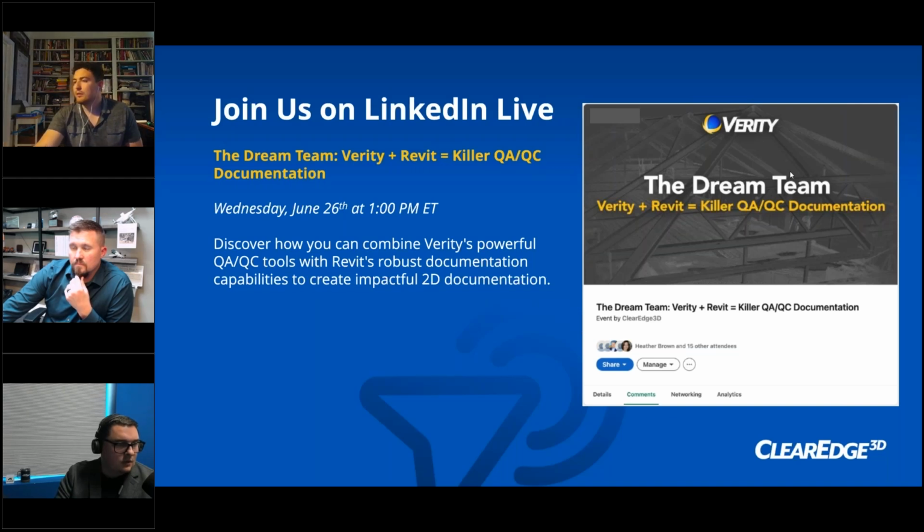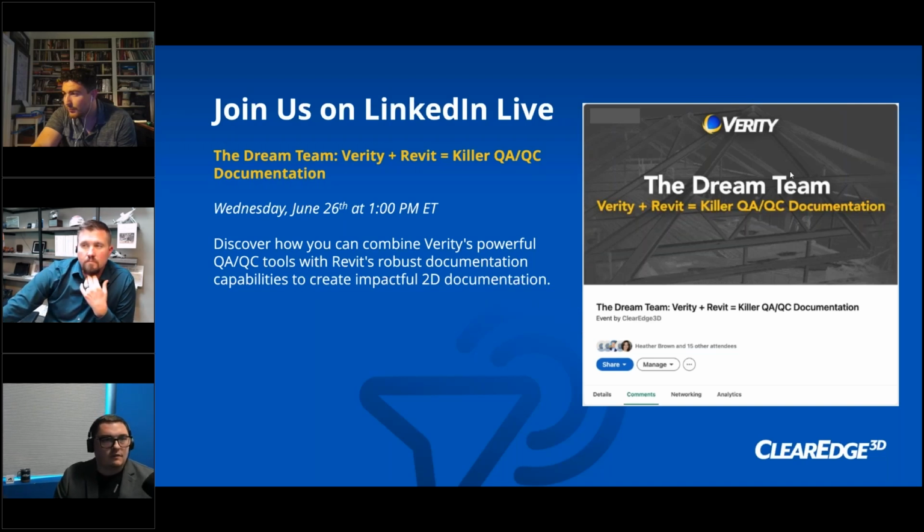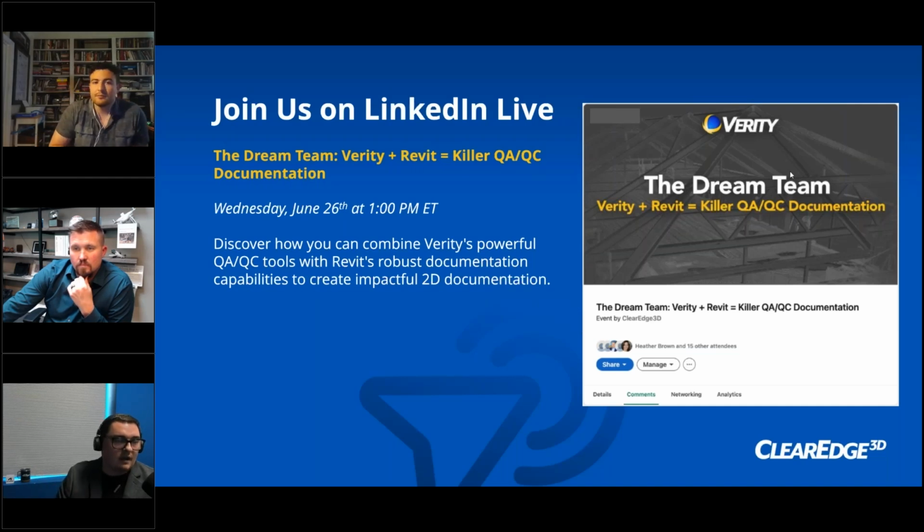And then I saw a question about point cloud data and creating models. Just going back a couple seconds ago to Trevor's point, ClearEdge 3D has an amazing software called Edgewise. If you're working from nothing and you're trying to create a Revit model, it can actually analyze the point cloud, very similar to what we saw today with what Verity was doing, and actually understand where the objects are. Edgewise software, though, is a dedicated BIM modeling software, so it's actually outputting Revit or CAD files of your 3D model and basically running through and analyzing that data.